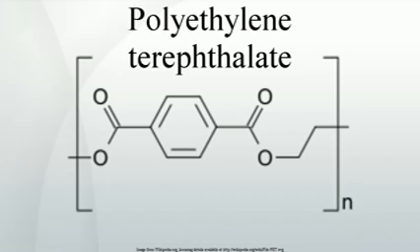Partial glycolysis. Partial glycolysis, transesterification with ethylene glycol, converts the rigid polymer into short-chained oligomers that can be melt-filtered at low temperature. Once rid of the impurities, the oligomers can be fed back into the production process for polymerization. The task consists in feeding 10 to 25% bottle flakes while maintaining the quality of the bottle pellets that are